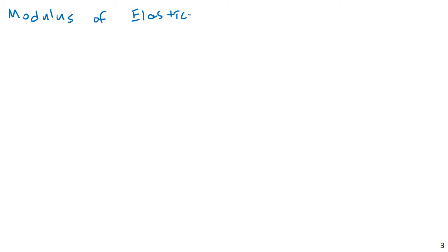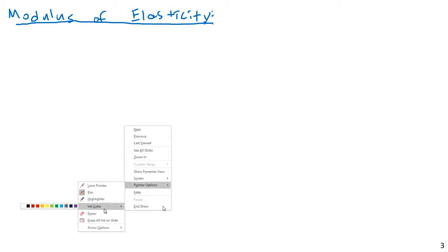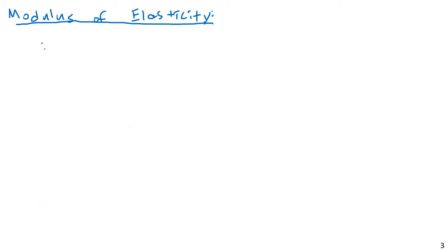Well, I should back up and say it will have a linear region. It will definitely have a linear region, but different samples of concrete will not have the same modulus of elasticity. We need to predict it based off of usually f'c. Although I suppose you could directly measure it as well, and there are ASTM standards that you can do that. But anyway, usually we just use the formula present in the manual, in the ACI code, to calculate it based on f'c. So Ec, capital Ec is the term that we see in the ACI code. And this is simply the modulus of elasticity of concrete, of your given type of concrete.